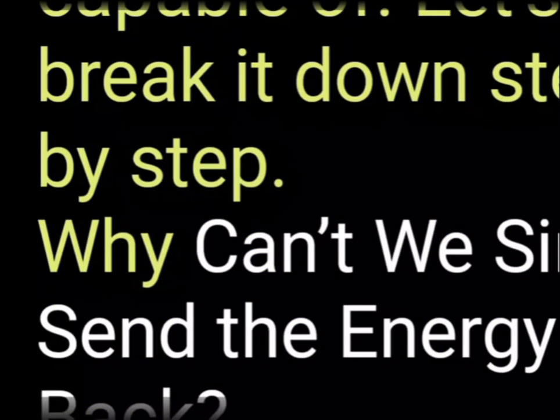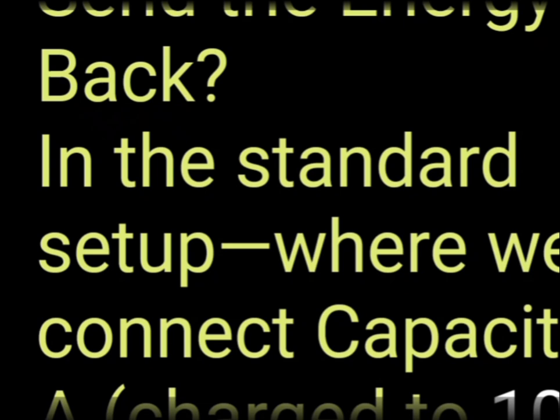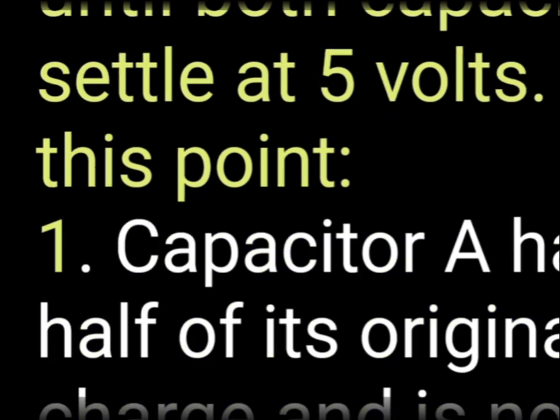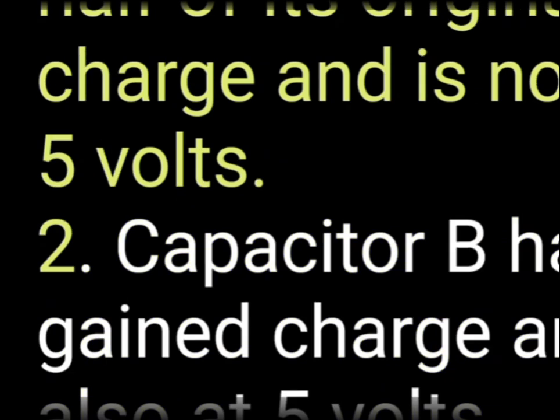In the standard setup, where we connect capacitor A, charged to 10 volts, to capacitor B, uncharged, charge redistributes until both capacitors settle at 5 volts. At this point, 1. Capacitor A has half of its original charge and is now at 5 volts. 2. Capacitor B has gained charge and is also at 5 volts. The total energy remaining in the system is half of what we started with.